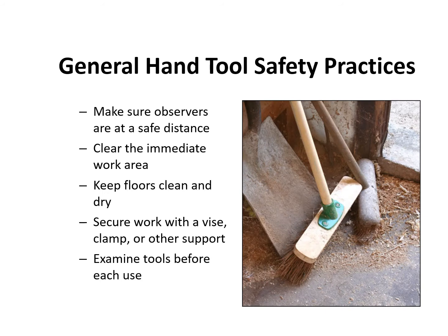Hand tool hazards and injuries can be avoided by practicing general hand tool safety. Make sure no one is standing near you when you're using the tool unless they are wearing appropriate protective equipment. Anyone watching the work or working nearby could be injured. Create a safe work area by removing objects that may get in the way or that you could strike if the tool were to slip.